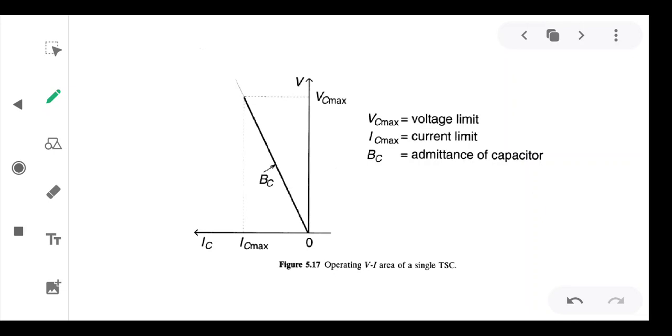So by having the switching operations in a transient free manner, you can reduce the overall harmonics injected by the SVC with the help of the TSC, TCR type SVC. So in TSC, TCR type SVC operation, you need to operate TSCs in a transient free manner and TCR in minimal harmonic injected mode to the system, so that you can gain the maximum benefits out of the SVC.